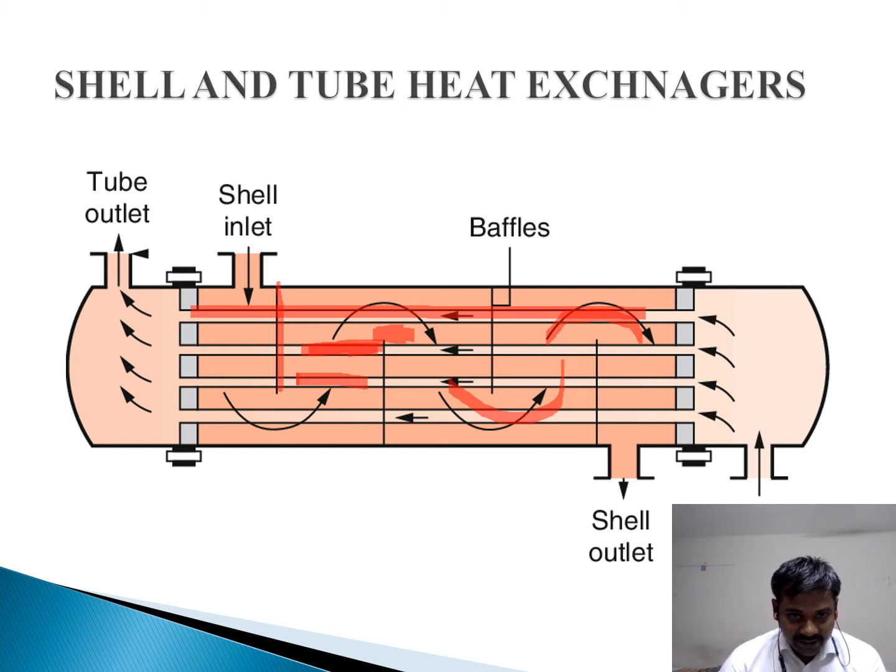If your surface gets heated, that is conduction, because conduction takes place at solid surfaces, and with the help of the fluid movement, the heat is transferred. That is because of convection. So this is the general construction and working of your shell and tube heat exchanger.